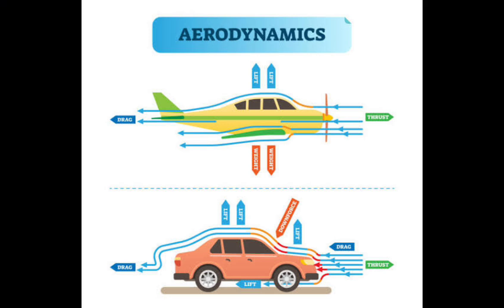This is where the Bernoulli principle comes into play. This principle states that faster moving air exerts lower pressure, so the air pressure on the top of the wings becomes lower than the pressure on the bottom. Imagine there's a higher pressure underneath. The wing is literally pushed upward toward the area of lower pressure above. This pressure difference creates an upward force we call lift.